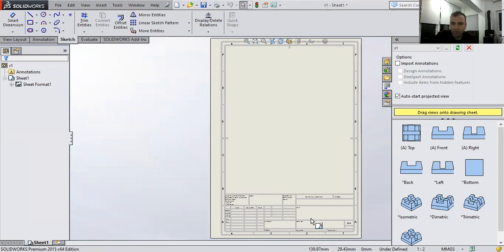Okay. If you have a look at this part from your left side, definitely it will be the left view. And even it's possible to have a look at the part from the top. That's why this view is called the top view. Okay, you can see the part from the bottom. It will be the bottom view, and you may see the part from the back. It will be the back or rear view. So for any part, we can have 6 different views.